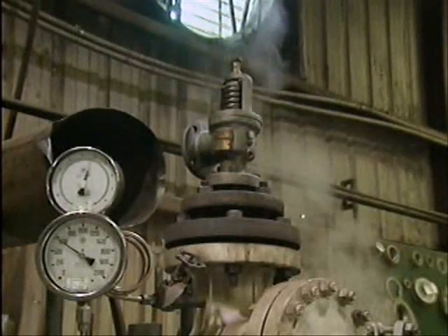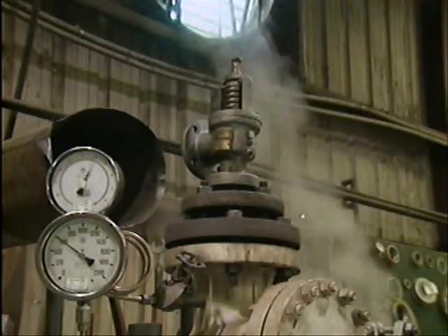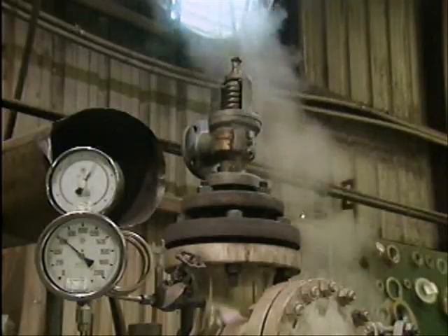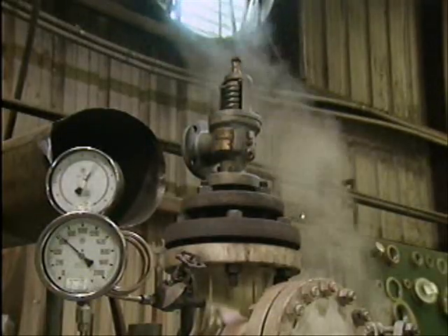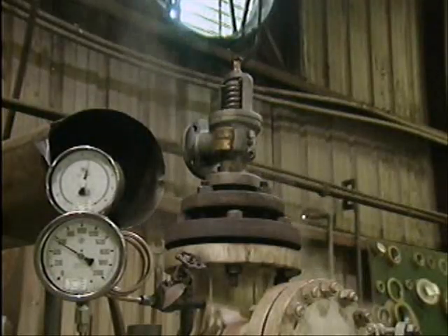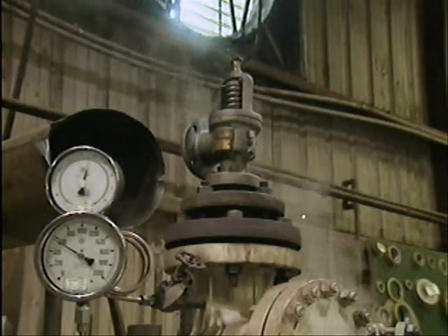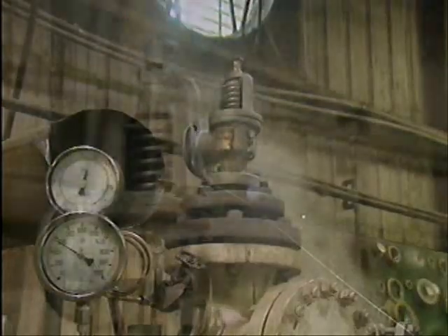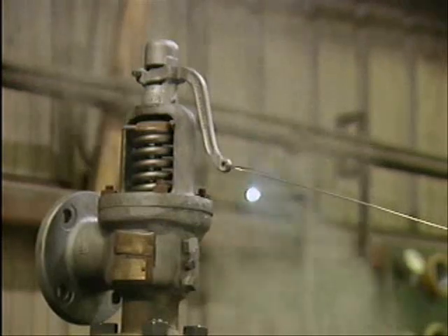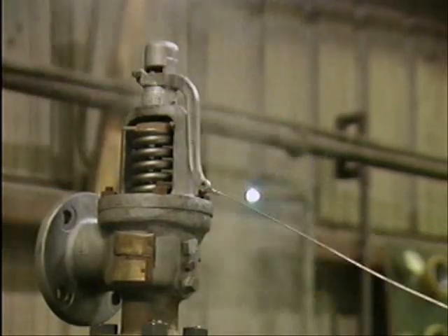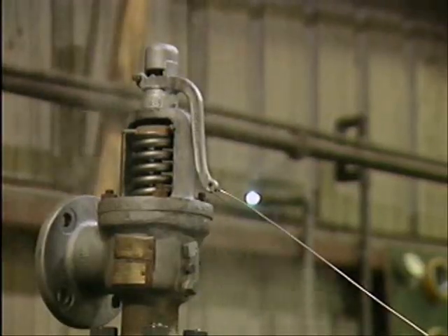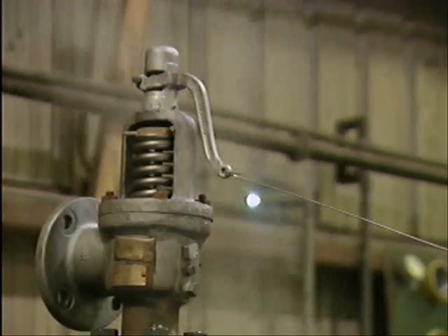An external inspection may reveal that a valve is leaking between the disc and the seat. This could occur if the valve didn't reseat correctly after the last time that it popped. Or it could be caused by foreign matter, such as ash, dirt, or rust particles trapped between the seat and the disc. In many cases, you can correct either of these 2 causes of leakage by manually lifting, or hand lifting, the valve. Hand lifting clears foreign matter out of the valve and gives the disc a chance to reseat